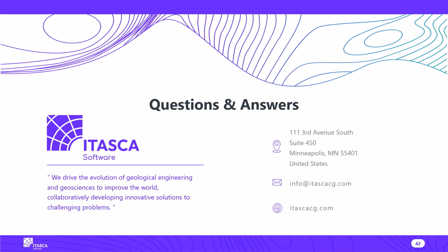stresses. So you get that by imposing the cave geometry, and what is key in this process is resetting the stresses inside the cave and putting residual properties. So by putting zero stresses initially, you are able to capture the redistribution of stresses and the abutment stress, which is the one causing the damage in real life, and in this case in the model.